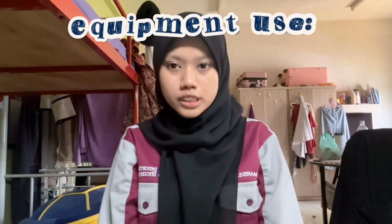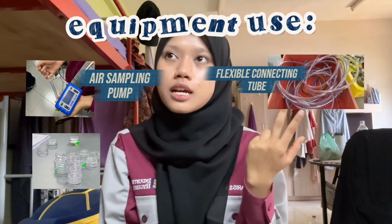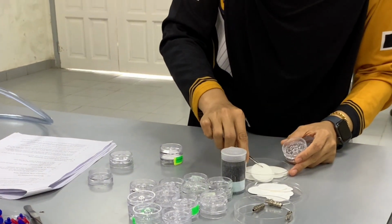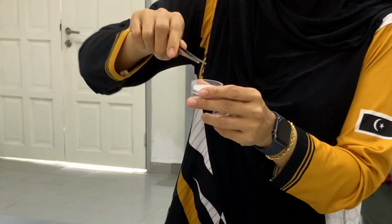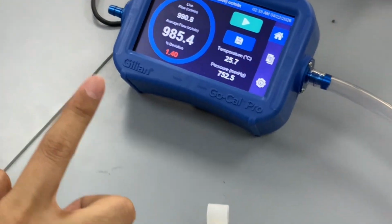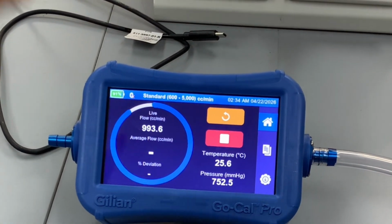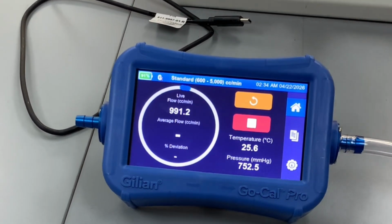The equipment used for this monitoring includes an air sampling pump, a flexible connecting tube, an MCE filter cassette, a calibration device, or a reviver plug when required. Inside the cassette there is an MCE filter paper which acts as the main collection medium where airborne lead fumes are trapped on its surface. The air sampling pump is used to draw air through the system at a controlled flow rate, while the connecting tube links the pump to the cassette. The calibration device is used to make sure the flow of the pump is accurate before and after sampling.